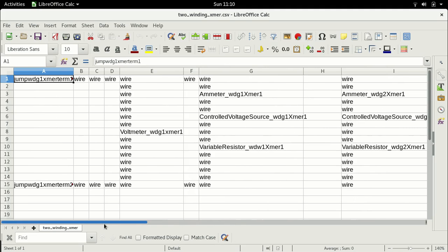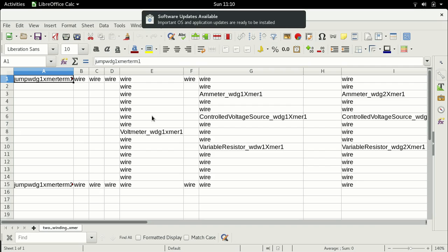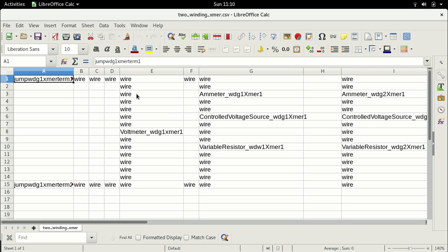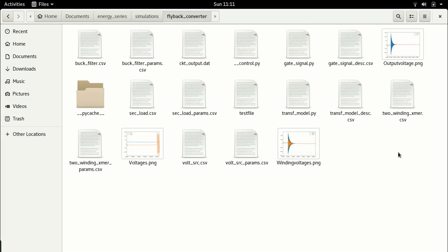This is essentially the trick in the flyback converter, that it allows the primary to take energy from the source when the switch is turned on, and when the switch is turned off, the magnetic energy stored in the magnetic field in the transformer is discharged through the secondary to the load. So in essence, this is where we had left off.